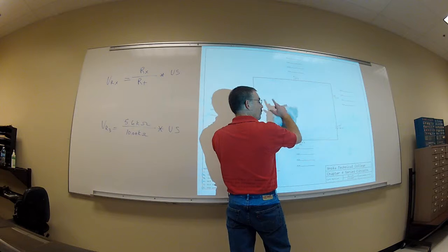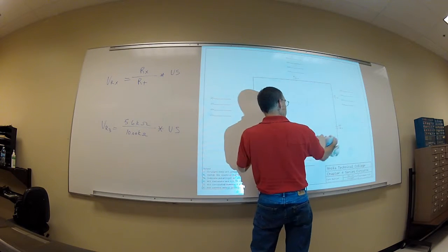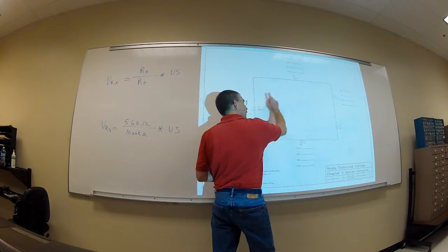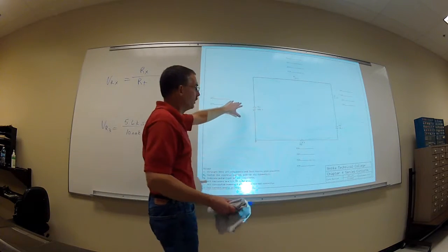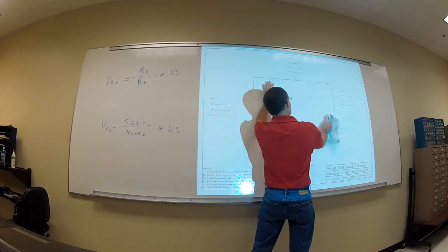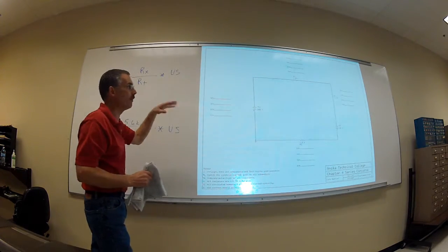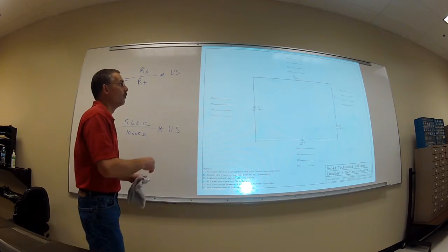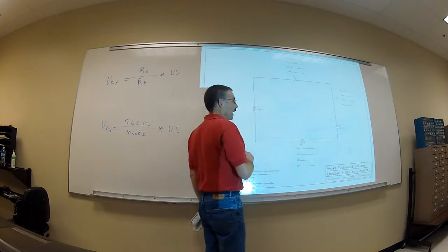It doesn't matter in a series circuit where our components are or where our power supplies are. The current is still going to flow the same way. The source voltage is still going to have the potential energy of moving those electrons around. This one is really demonstrating that it doesn't matter in a series circuit. I can mix these components all around, and I would still come up with the same numbers, the same current and the same voltage drops, no matter where these components are or whatever order they are going into that series circuit.